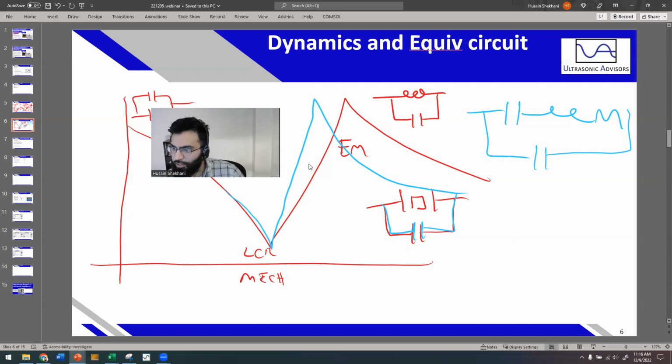There's a question: does the two capacitors in the added capacitor circuit overpower the inductor? How does it shift the impedance versus frequency? Basically, the frequency at which this inductor and this capacitance are equal in terms of output. As the frequency increases, the inductance is causing lower and lower current, and the capacitor is causing more and more. So there's a point where they meet, and that is the optimal cancellation point.